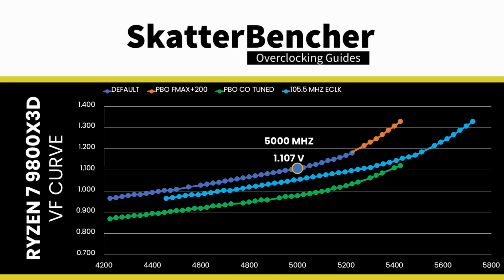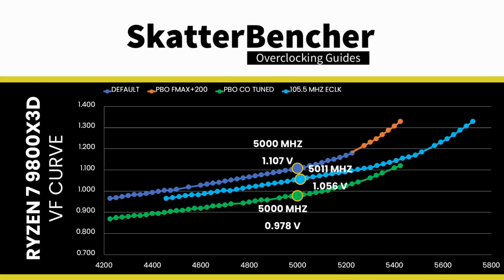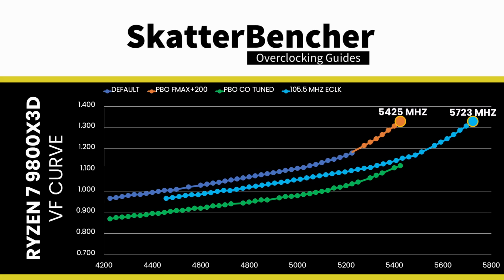For example, for 5 GHz we need 1.107 volt by default, about 1.056 volt when using 105.5 MHz eCLK, but only 0.978 volt when curve optimized. Third, the curve now extends well beyond the 5450 MHz Fmax, for which there's no guaranteed operating voltage defined by the factory fused VF curve, so we don't know if it's stable over there.